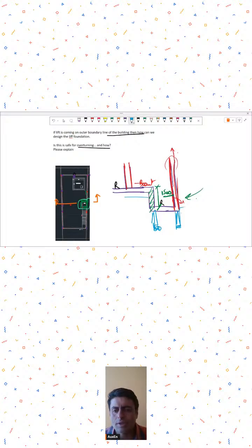And because you are not able to extend the footing beyond this face, in that case, assuming that there were very high lateral loads, I am answering this. One of the options, if your soil strata is weak, like clay or sandy strata, is that you can have piles provided just below.